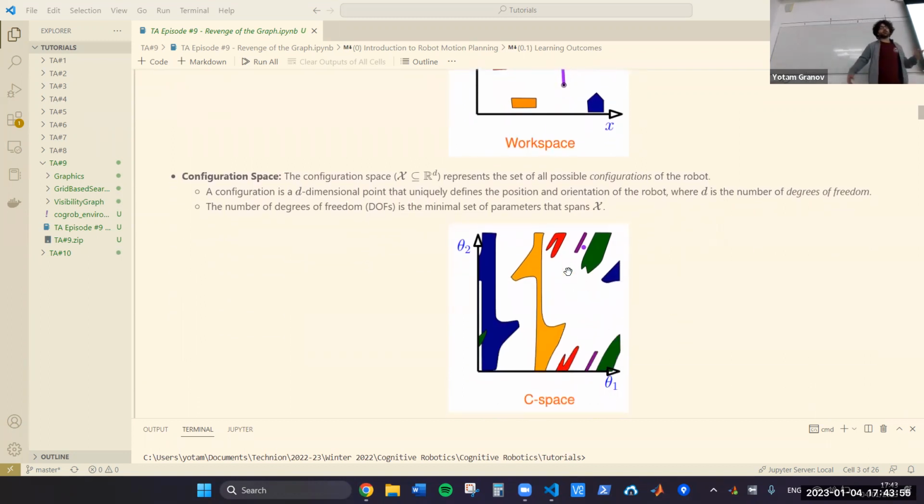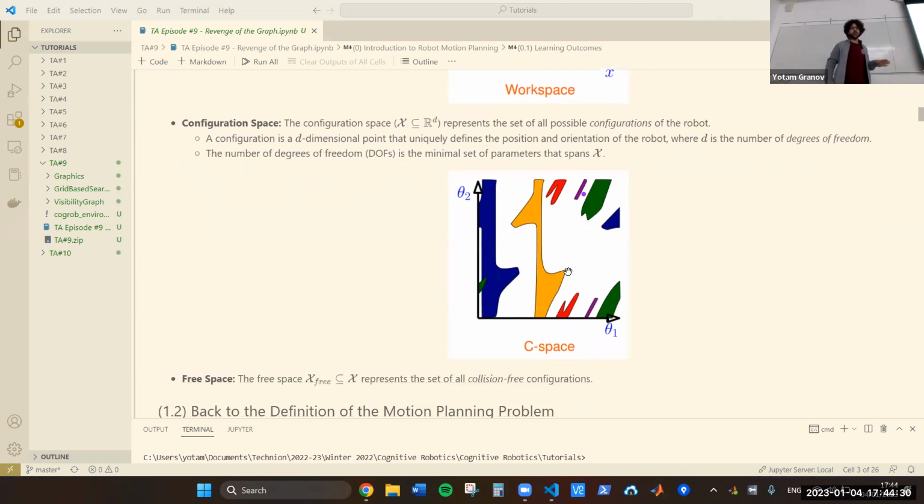Unfortunately, though, we can't just tell a robot arm to move to point XYZ, because robot arms don't really function that way. They have motors, and the motors have to rotate a certain angle to translate linearly. So it's not as simple as just telling a robot to move to point XYZ. We need to first tell it, well, what should the values at the joints be? What angle should it rotate among its many joints in order to reach the desired XYZ position? This problem is called inverse kinematics. We want to know what joint values we need to get to a certain point. We're not going to discuss inverse kinematics, but you should have seen it in the lecture I think last week.